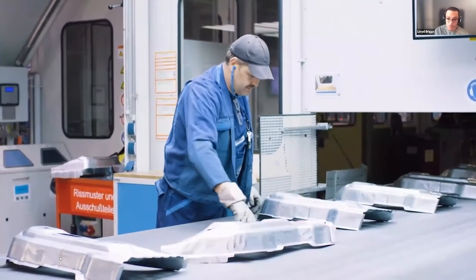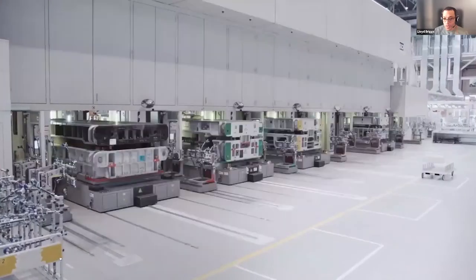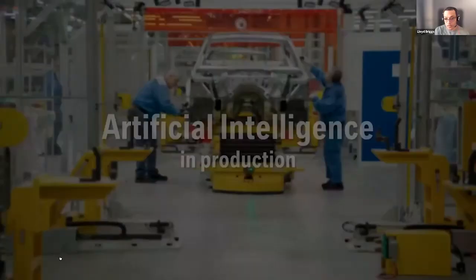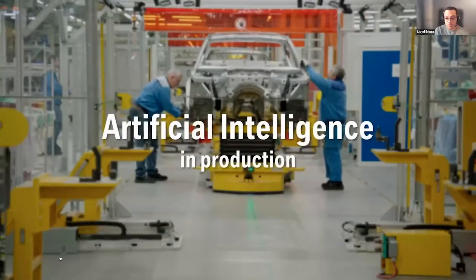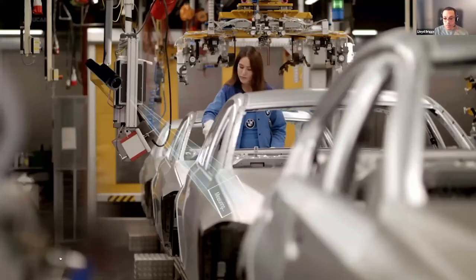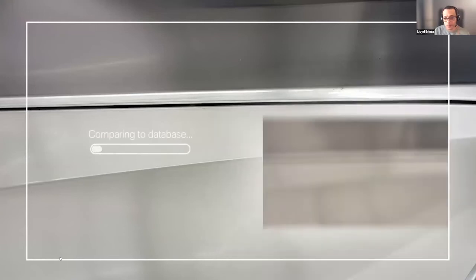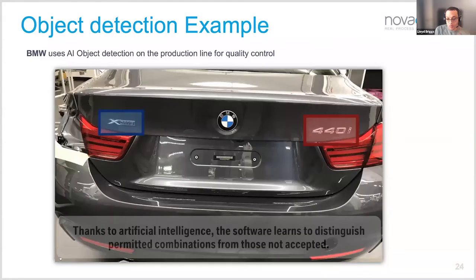So that panel's been rejected because it's out of spec. An operator doesn't have to check each panel with his own eyes anymore. He doesn't have to stand there all day looking at panels. And on the production line, on the trim line, you can see here that it's identifying the distance and measurements of gaps between the body panels. If the gap is too big, then that car will be put onto the rework line, because that car cannot go to a customer if the quality specifications haven't been met.